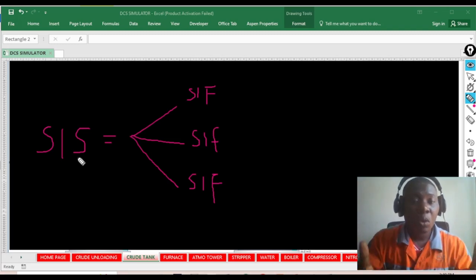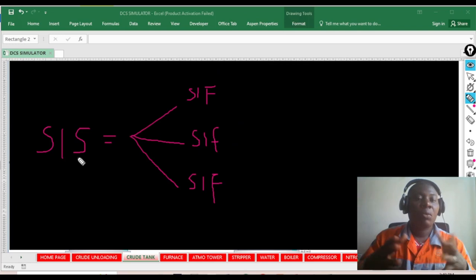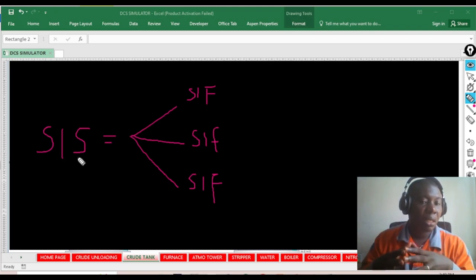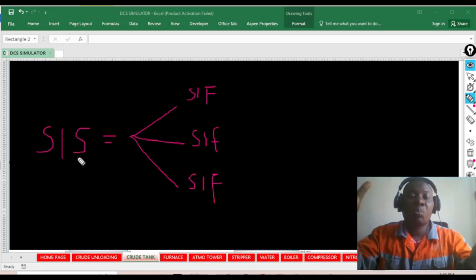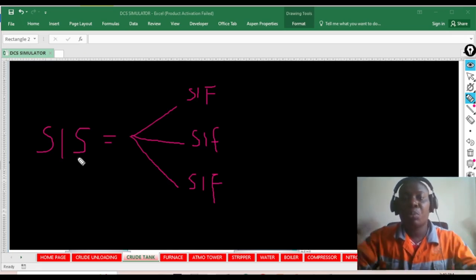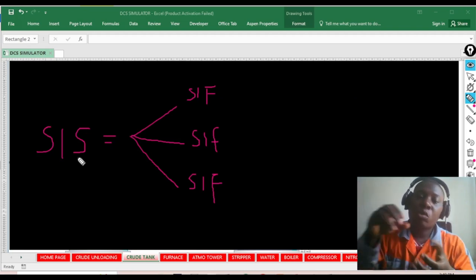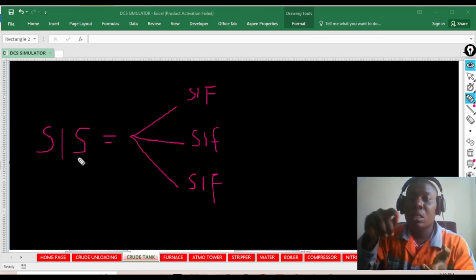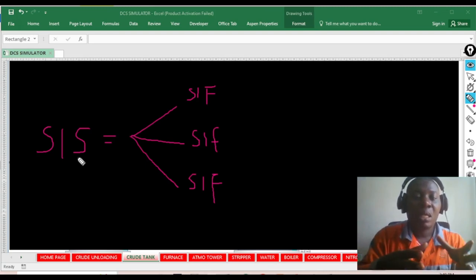We have operator response, which is also part of it. Alarms are part of it. We have the emergency response plan or preparedness, which is also part of it. We have the dike. In a tank farm, we have a bund wall that protects when there is a spill, so that it doesn't spread to other parts of the plant. That is also a layer of protection. Today we are just explaining one particular layer, which is the SIS, the safety instrumented system. Now we are talking about SIF.